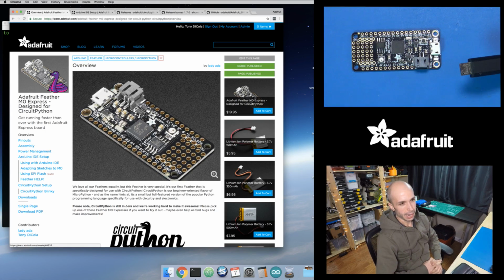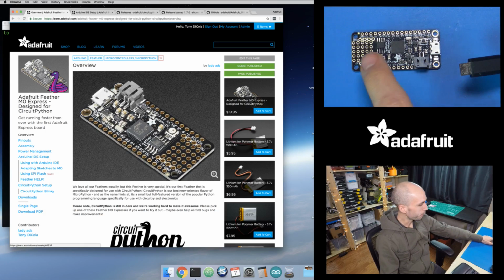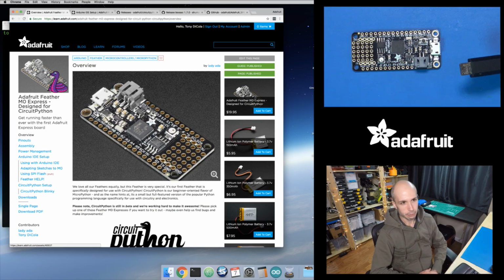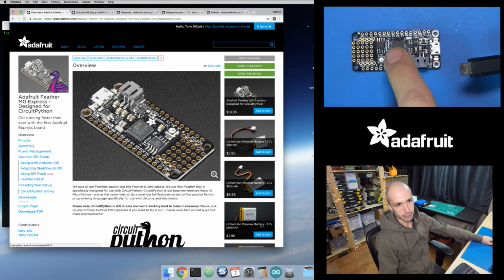As we've started to add more features to CircuitPython, we've run into a lot of problems where it's like, boy, it'd be really cool to add things like infrared LED support, like IR code sending and receiving, but we don't have the space maybe for that necessarily. So that's where that little flash chip comes into play, this thing right here. This is a 2 megabyte flash chip that's connected to the SPI bus. So it's just another SPI device. It uses the serial peripheral interface, and it's connected to the SAMD21 microprocessor. So it's just an additional set of memory and a significant memory upgrade. So 2 megabytes, that's quite a bit more. I think that's 8 times or so more space than what's on the microprocessor itself.